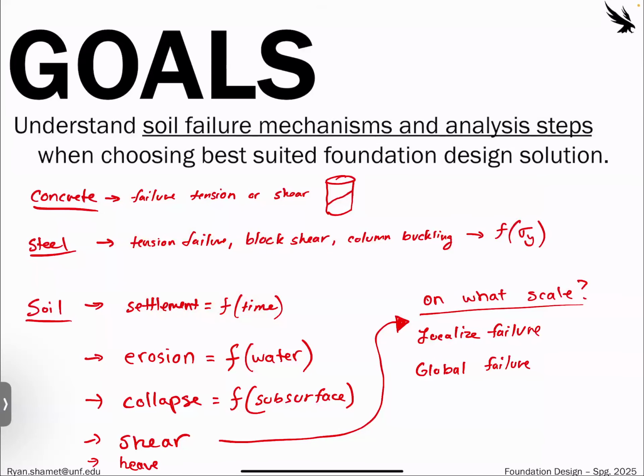Is heave related to when we have to look out for frost depths for buildings? Yep. Heave, that's why a lot of times, well, it could be either way. Frost depths are meant to protect the building. So up north, a lot of buildings will just be on piles anyway, so you don't warm up the ground and cause differential settlement, or so the building doesn't pop up in a certain area.